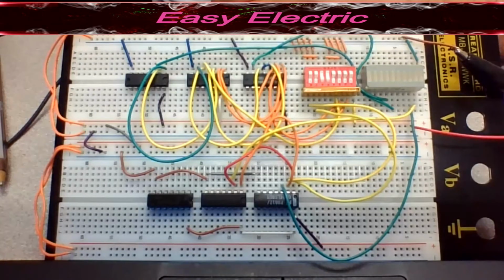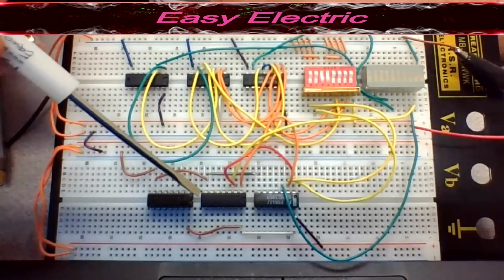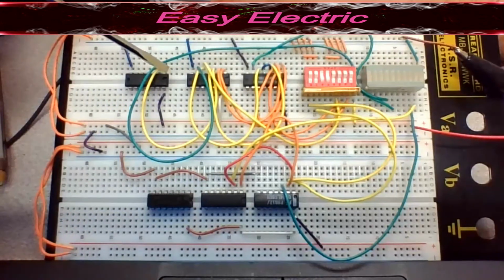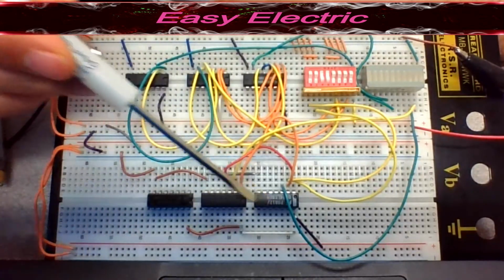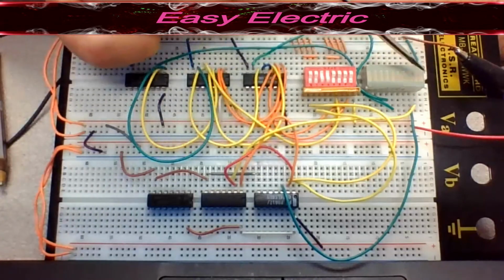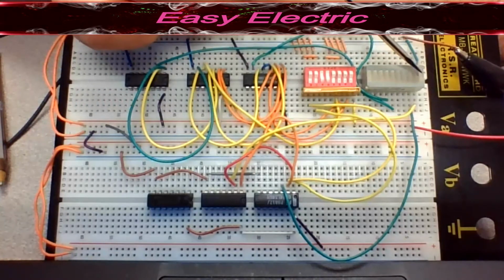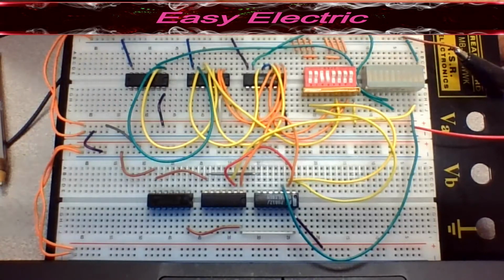So after simulation, let's implement the circuits with the ICs and the digital gates and see if the circuits work or not. Here we implement both circuits. In this section we implement the half adder. In this section we implement the full adder. Let's start with the half adder. We use these two switches for the inputs A and B of our half adder, and we use these two LEDs as the output of the half adder. This LED here is the highest value, this is the lowest value.